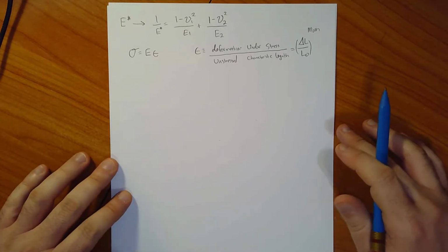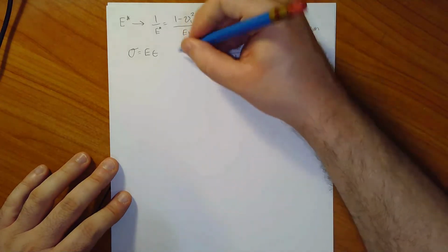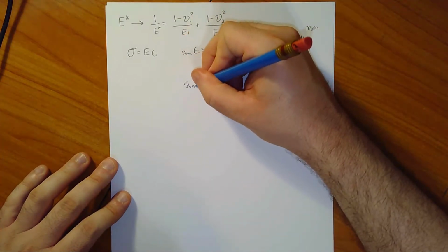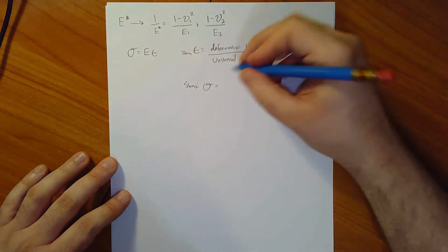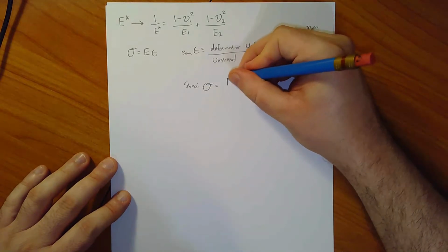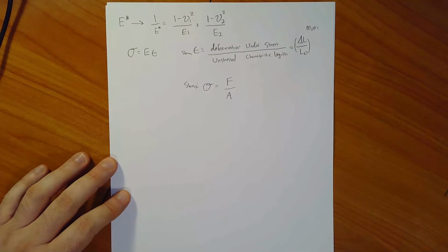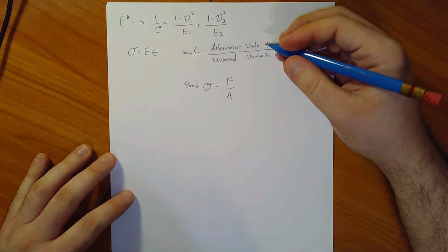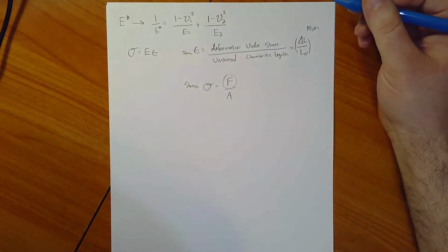Okay, so that's the strain, and let me write that. Then what's the stress? That's the sigma, and stress is just a pressure, right? It has units of pressure, the amount of force acting over some cross-sectional area inside whatever object you're putting under load, and it's actually this force that we want.